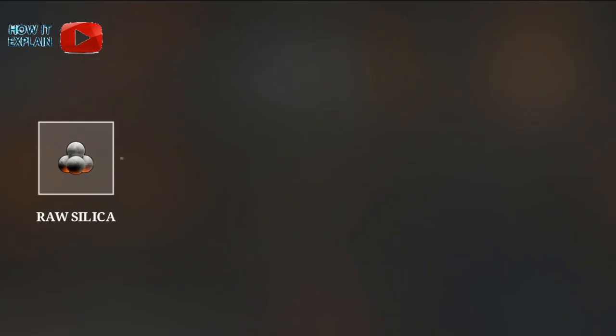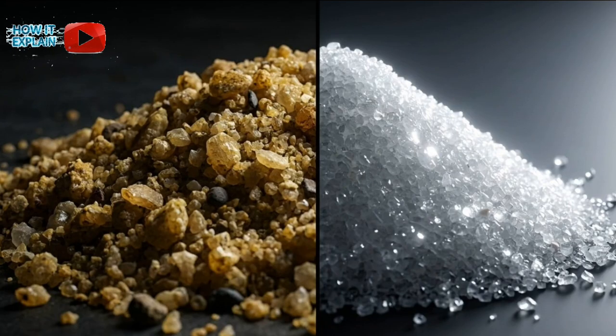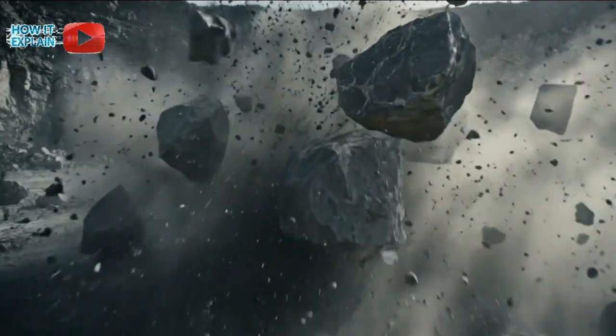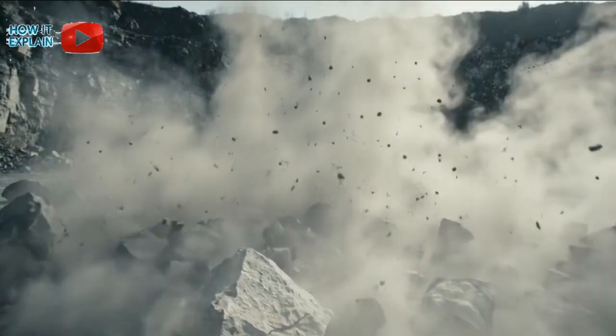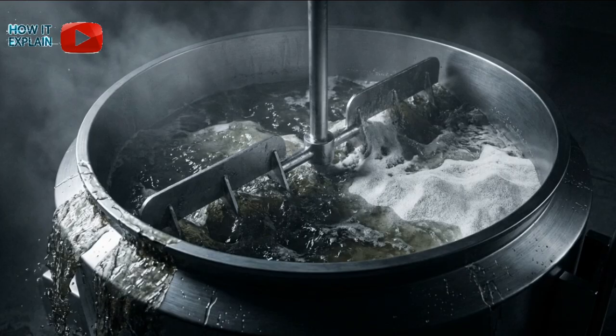Producing the high-clarity glass used in modern technology requires a sophisticated sequence of thermal and chemical engineering. Modern manufacturing requires sand far purer than what you find on a beach. It begins in quarries, where dynamite blasts apart rock faces to reach quartz containing 99% pure silica. Massive industrial mills grind these rocks into a fine powder. From there, industrial washers scrub 220 tons of sand every hour to remove surface contaminants.